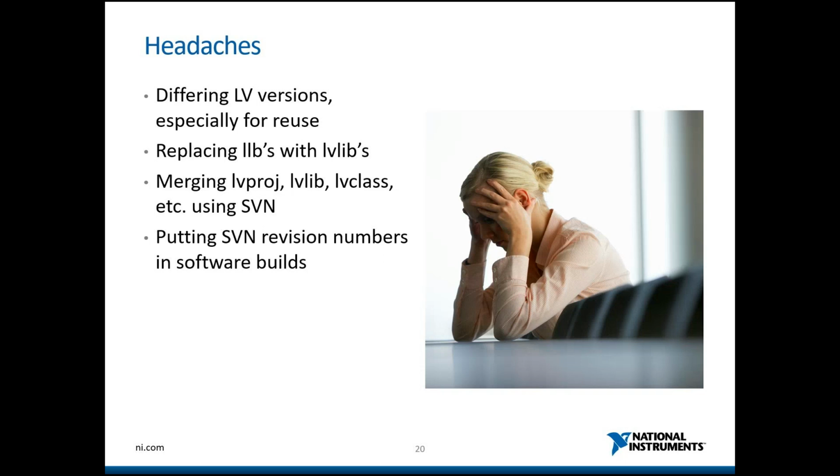Yes, absolutely, Kevin. I always try to separate it. It makes checking in and out a lot better. So I personally always separate compiled code. Yes, it's the default, and it is difficult to use. If you go into project settings, I think there's a setting that says all new VIs in this project, mark them as separate compiled code. And I think it pulls up a table and lets you change them all in bulk too. So it's not as hard as it used to be.